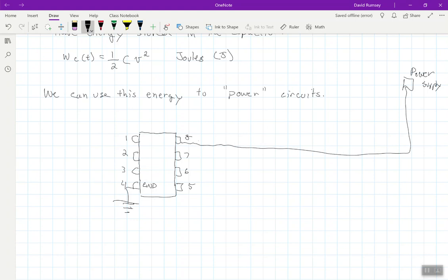Now anytime this chip needs more power, needs more current to do whatever it is, for instance, if it's an op amp and you're amplifying an audio signal, those things are going up and down, so it's having to change its state rapidly, so it's needing current to do that. It's got to go all the way back to the power supply to pull that energy and pull it down this entire trace here.